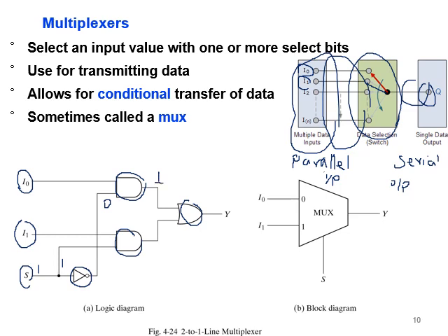I0, sorry, it will be 0 because it's multiplied by 0. But here I1 will appear, whatever it is. If it is 0, 0, if it is 1, 1. And at the end here I1 will appear. You see? Let's assume the opposite. Let me take another color. Here 0, here 0, here 1. Nothing will appear here, but here I0 will appear. And at the output, it will appear I0, whatever it is, 0 or 1.